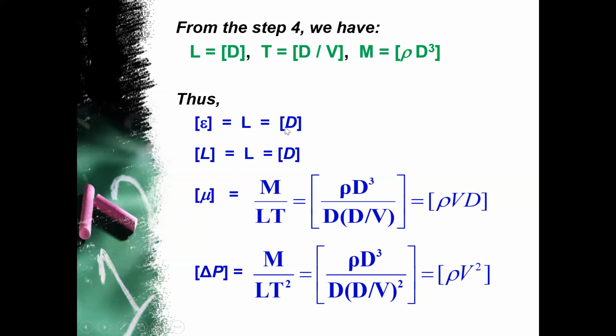equations, all right? So for example, the epsilon now is becoming D, all right? The length of the pipe is becoming D, diameter, all right? Diameter of it, because remember, the purpose of this is to obtain a dimensionless group, right? This is the purpose, right? Because if this one, the surface roughness, is in the dimension of L, the D also contains the fundamental dimension L. So if you take this one divided with this one, you'll be dimensionless, right? It's the same with this one. This is the trick. For all these 4, you'll be the same, all right?